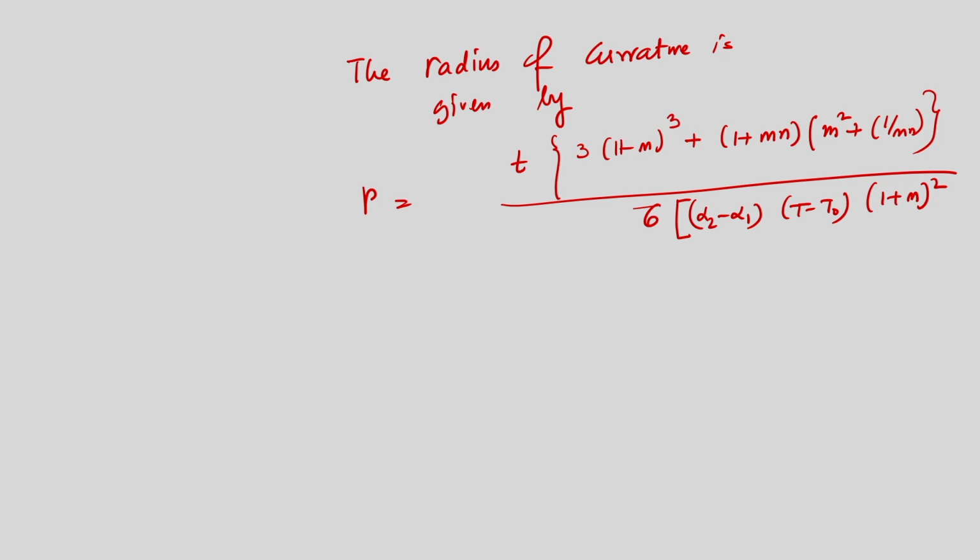Now, this formula is most useful as a design guide, as we will never know the material properties to sufficient accuracy, so it can be used as a mathematical structure for calibration. It can also be used to directly measure temperature without any calibration, by knowing the radius of curvature.